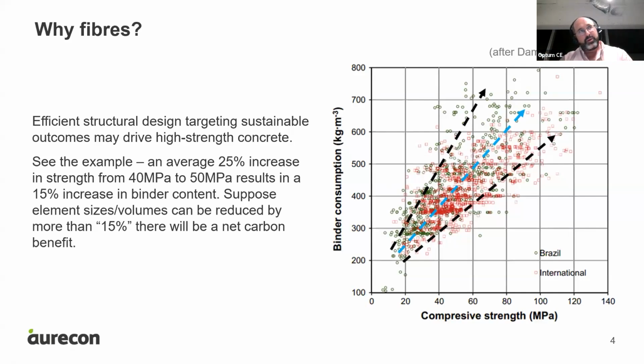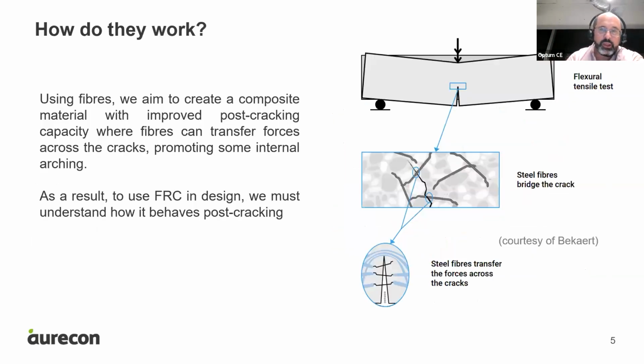So some of the benefits, we always think, oh, look, I might not need to use higher strength. But if you're thinking of using higher strength and optimizing your design in terms of thicknesses, dimensions and volumes, you may get the benefit. But there are some implications when you start using high strength concrete. You need to think about ductility and the implications, particularly when you're combining with fibers, which we're going to discuss very soon. But how fibers work, we really have to change our mindsets when thinking about fiber-reinforced concrete,